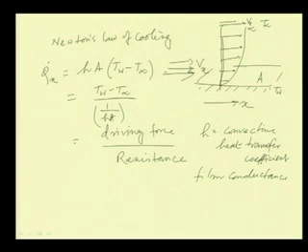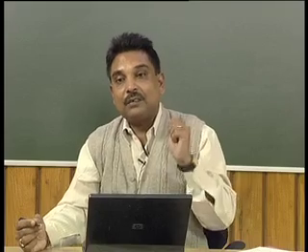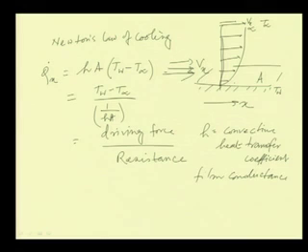And we can understand that, as it is a phenomenon happening because of these layers, and the transport takes place between the layers till the free stream conditions, h should be a function of fluid and a function of flow conditions.